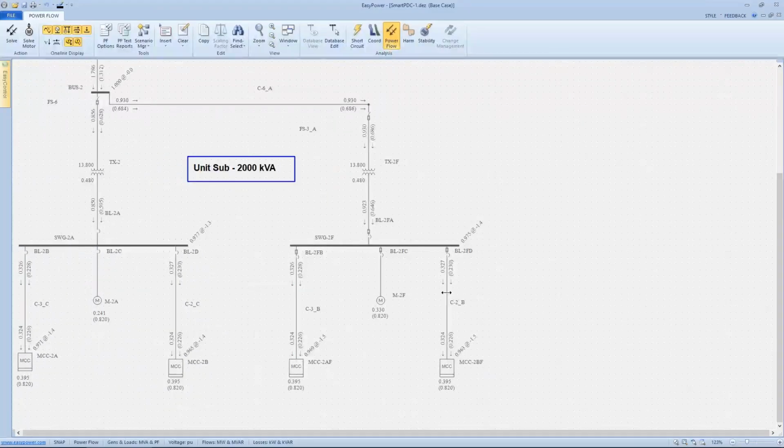Putting in more cables to reduce the resistance here isn't necessarily the thing to do. The tool itself will show us the voltage drops at each bus. I'm up here on the top row: the generator data and load data, both in real power and imaginary power, and then the branch flows.